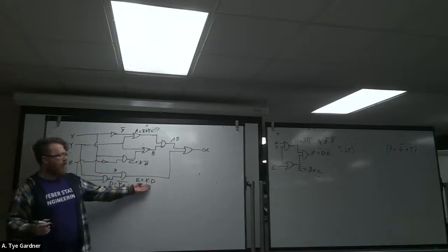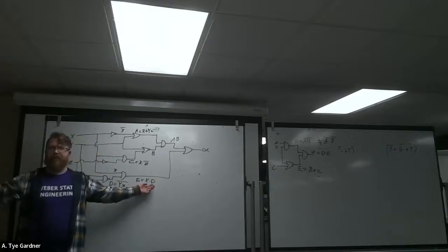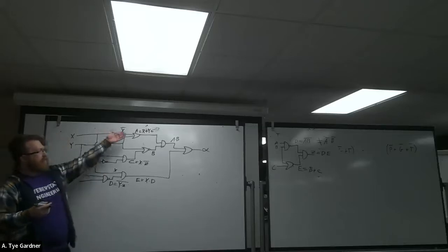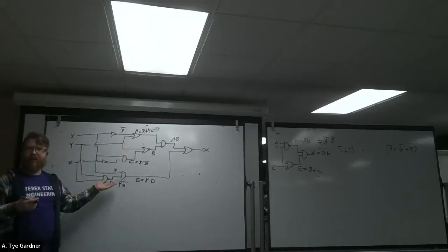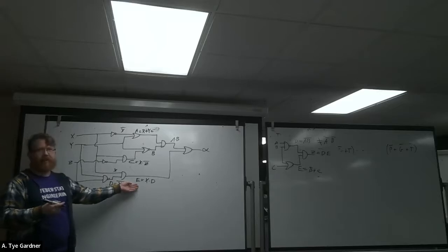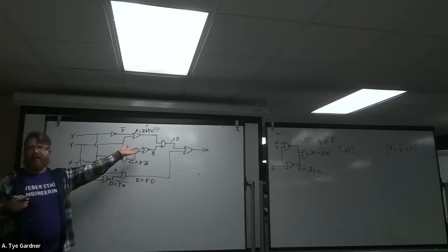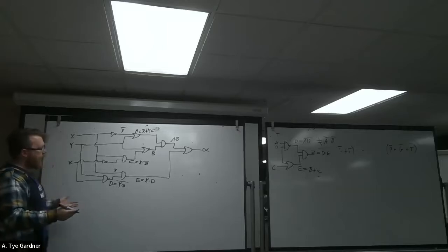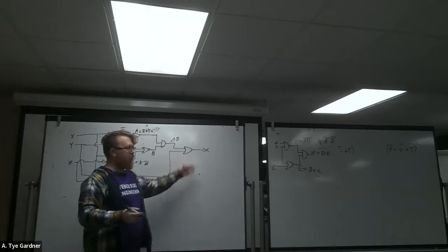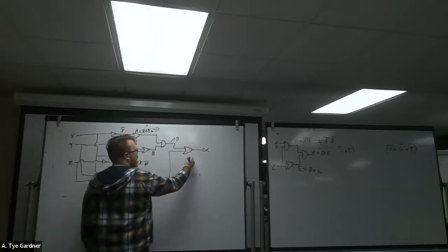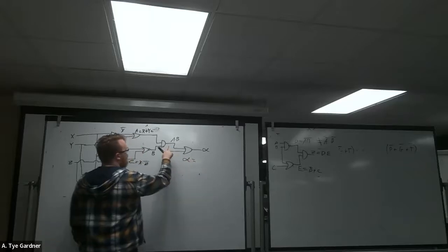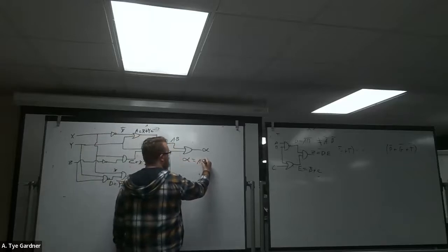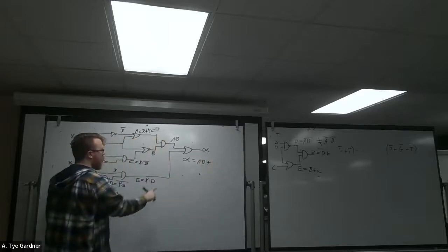Totally fine. To make an input variable and an intermediate signal, right? Because they are related. I'm going to do a substitution later. Make sure that you don't accidentally double up these new variables, right? That would get really confusing if I accidentally called this B or something and I had a B there and then I do substitutions. I don't know what's going to happen. And now we can ask the question, am I ready for my output gate? Well, my output gate is alpha equals, I didn't even give this a name, so that's okay. A and B or E.